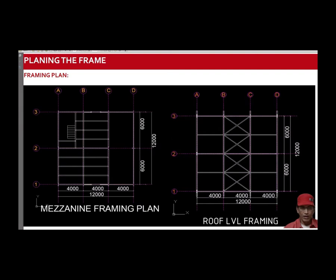Having gone through the architectural requirement or the requirement provided by the customer, the structural engineer now must devise a framing plan to provide a load path mainly for two kinds of load. There is gravity load and the lateral load. The gravity load consists of the dead load or any other kind of superimposed load and live load.